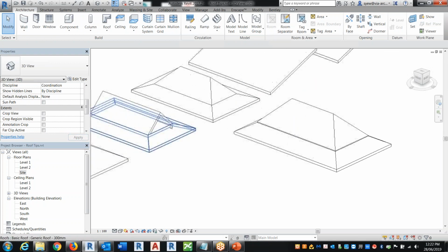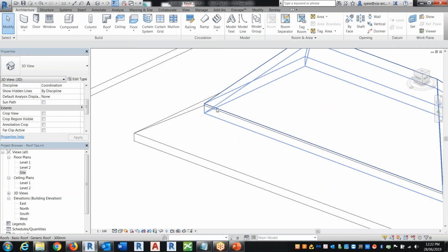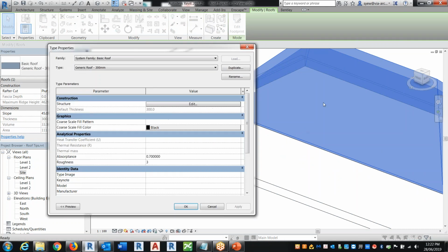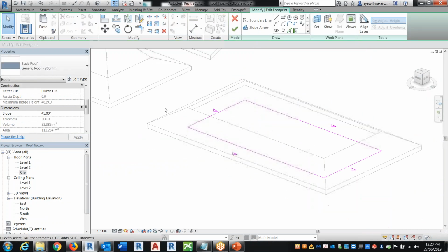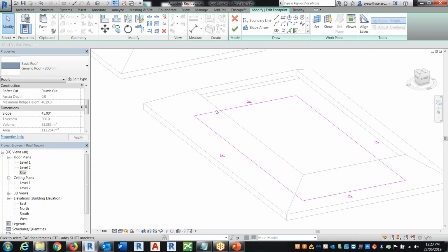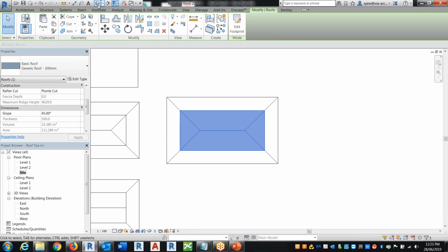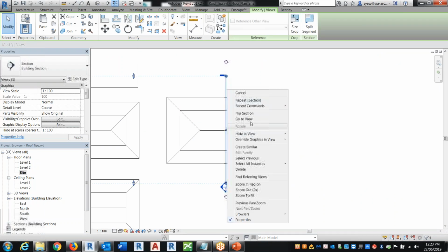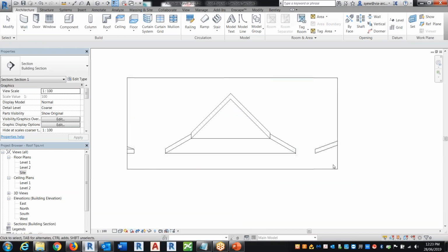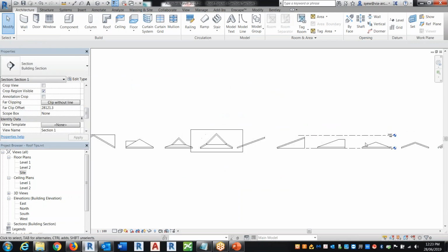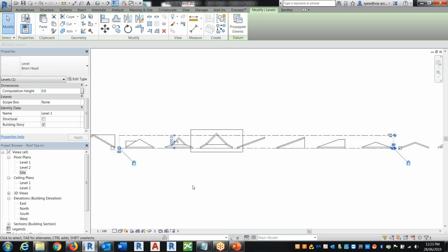That looks like that. Just keep in mind that once you change the angle, this thing will creep up. If you want to control it, typically how I do it is that for this roof, I would create like 2 things. The proper way of doing this is you go into the roof itself. Let's assume there is a level here. I'm just going to expand all and see if there's a level.